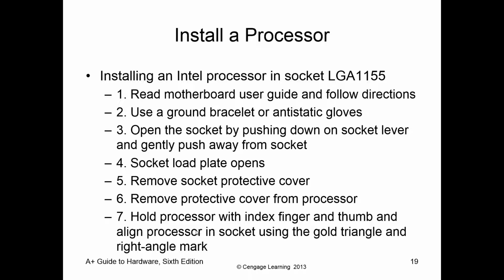Next, assuming that the motherboard is already installed, even if it's not, if it's on an anti-static bag, we're going to be opening the socket, and we do that by normally pushing down the lever that will hold the socket closed.